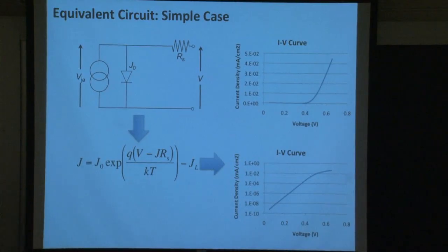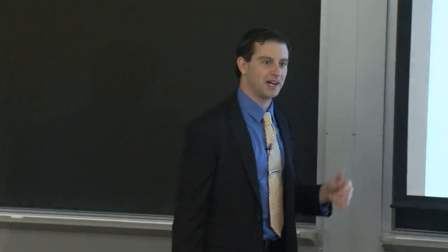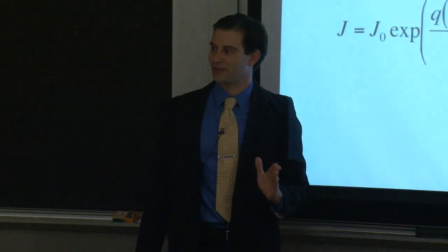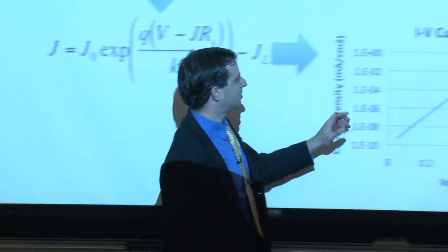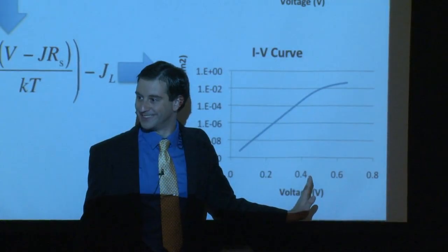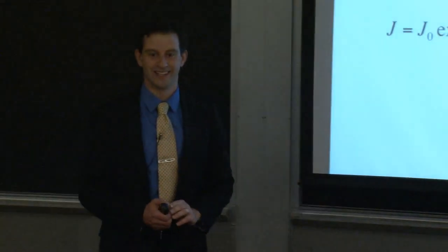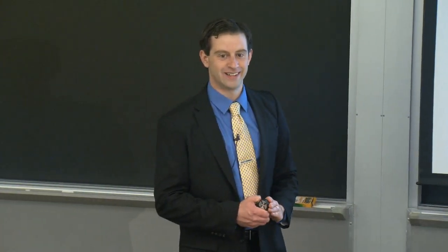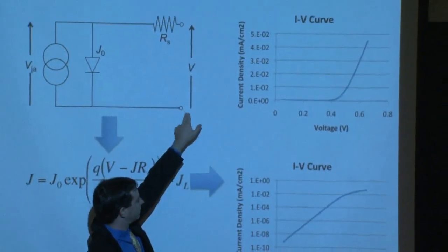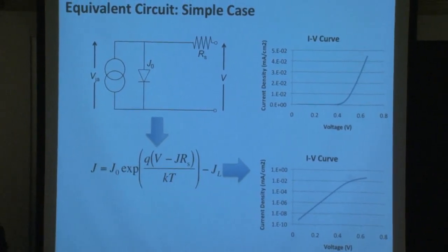So that's a very, very important and astute observation that the series resistance begins to kill you at high forward bias voltage conditions. You hope that you design your solar cell in such a way that the series resistance only really begins to kick in above the maximum power point voltage. That's the goal. And this is not voltage out, this is voltage applied to the battery? No, this is the voltage that is being measured across the solar cell. So that's output. The output voltage, yeah.